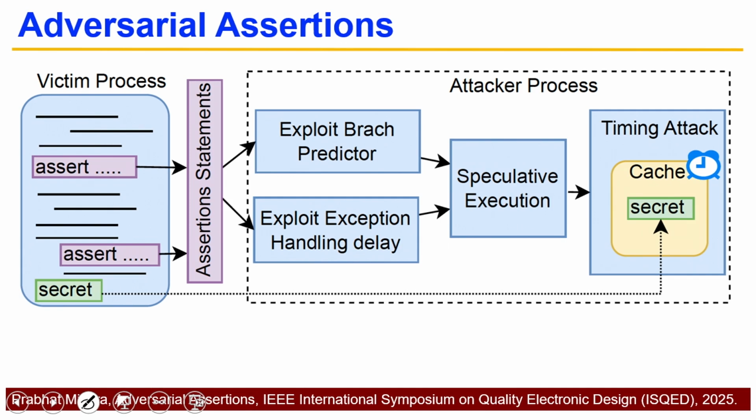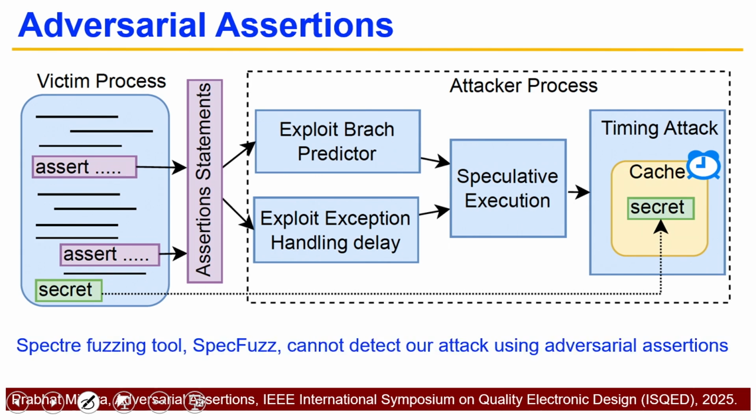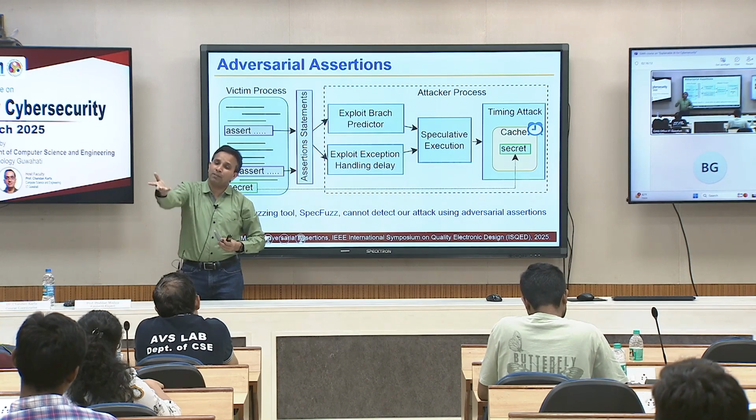When I thought about it, I realized it is exactly the same as the Spectre attack. Then I ran it through SpecFuzz. This is one of the tools that runs through your design, and I talked about different testing techniques, and fuzzing is one of those techniques. You can think about it as a random test pattern you run and check, but the only difference from normal testing is that it remembers what happened in the past.